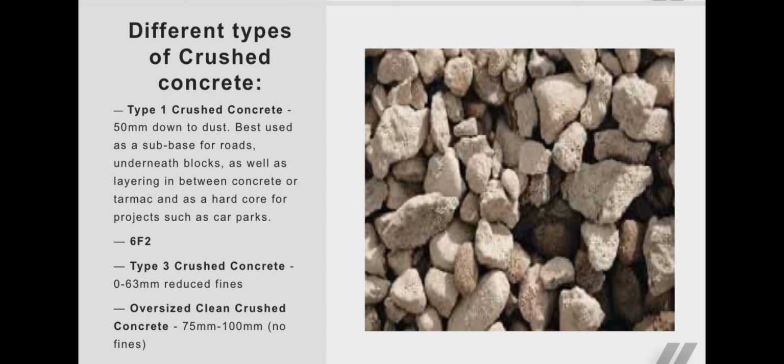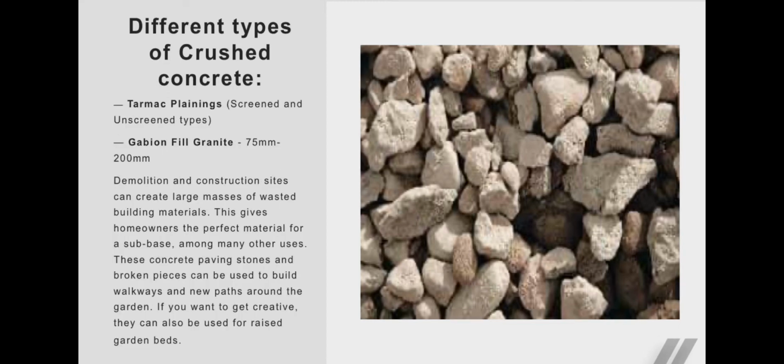6F2, type 3 crushed concrete, 0 to 63 mm, reduced fine. Oversized clean concrete, crushed concrete, 75 mm to 100 mm, no fines. Tarmac planings, screened and unscreened types. Gabion fill granite, 75 mm to 200 mm.